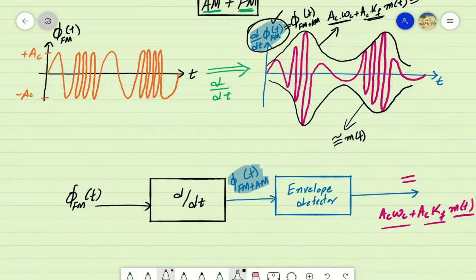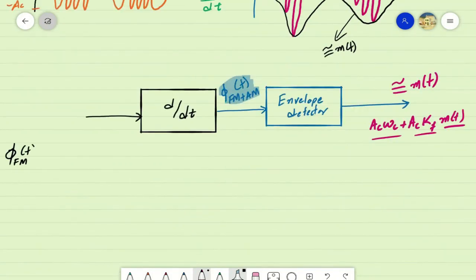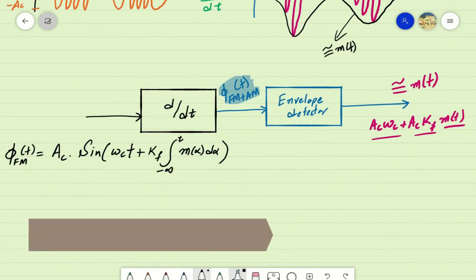So both the scaling and shifting parameters being constant and not being a function of time, we can express that the output is a direct representation of the information signal. This type of demodulator is also referred to as a slope detector because it detects the slope of the input frequency modulated signals. However, this form of demodulator has some challenges which can practically be encountered.